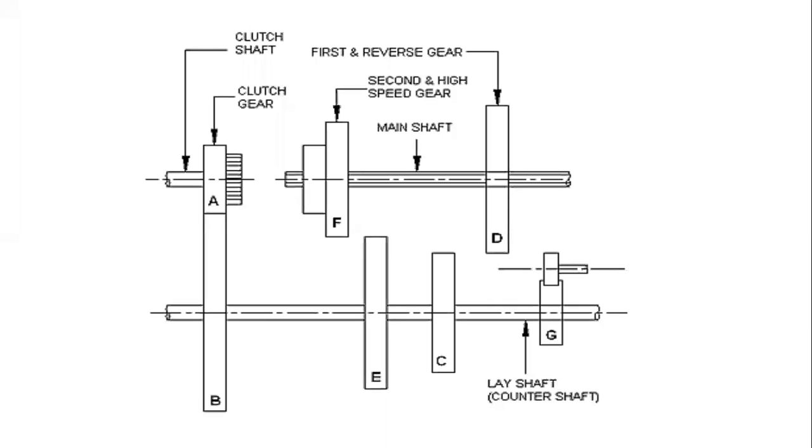is it possible to make all these stationary? It is not possible, is it not? Because your car is already moving. So in that case, I cannot use, in case of automobiles, such a sliding mesh gearbox. So this is used only in stationary applications, like in certain construction applications and in certain machineries where we can completely turn on and off the machines or the motions.